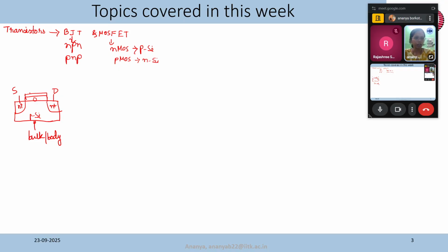Even if we make our devices very small, very thin, there will be no tunneling if we use high K dielectric, like we did in one problem last time. One example of high K dielectric is hafnium dioxide. There are other materials also, I'm not very sure about them, but we mostly discuss in terms of silicon dioxide. And then this is our metal terminal, which is our gate.